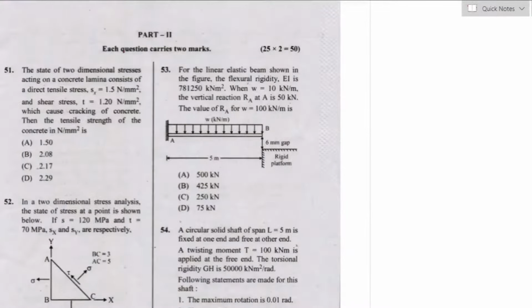Now let's begin with part 2 questions. Question number 51. The state of 2-dimensional stress acting on the concrete lamina consists of direct tensile stress, 1.5 Newton per mm square along x direction and the shear stress of 1.20 Newton per mm square, which causes cracking of concrete. The tensile strength of the concrete in Newton per mm square is...